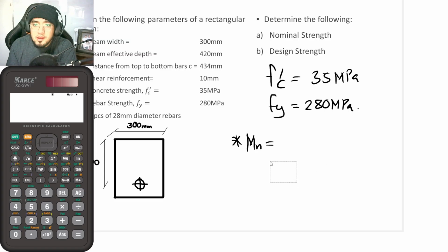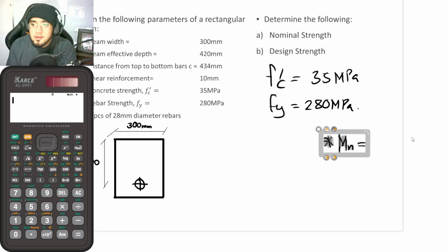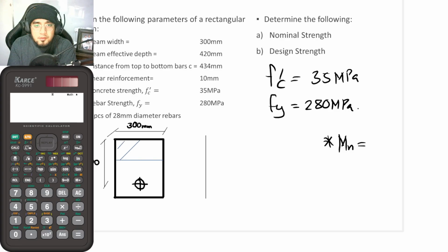Okay, so again, recap that for the nominal moment, Mn, you would either be getting the moment at the compression side or at the tension side, but once again, I think it would be better if I would be drawing the stress diagram here. Suppose once again that the compression concrete would now be this one here, meaning that this is now the uniformly distributed load.